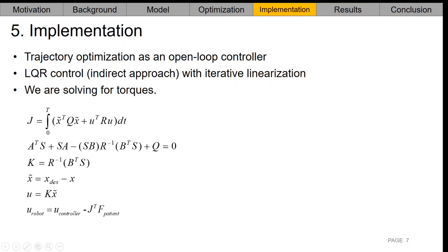The planner will output the desired manipulation trajectory. It will also provide the open-loop inputs to follow that trajectory, which works well in simulation. However, we need to employ a state feedback controller to stabilize the trajectory for experimental implementation. In this research, we have used LQR controllers. LQR is particularly useful for planar mechanisms.